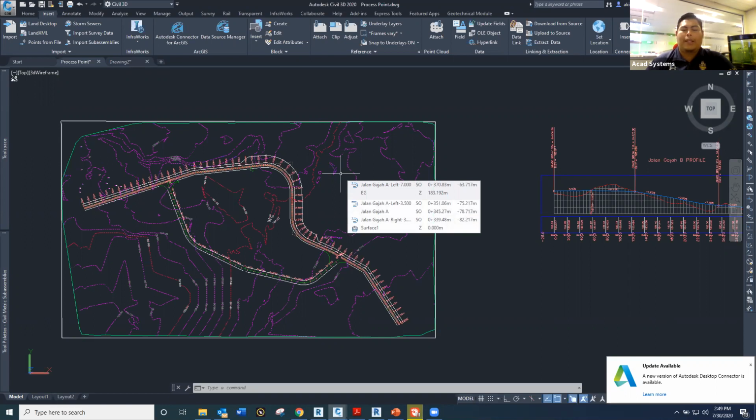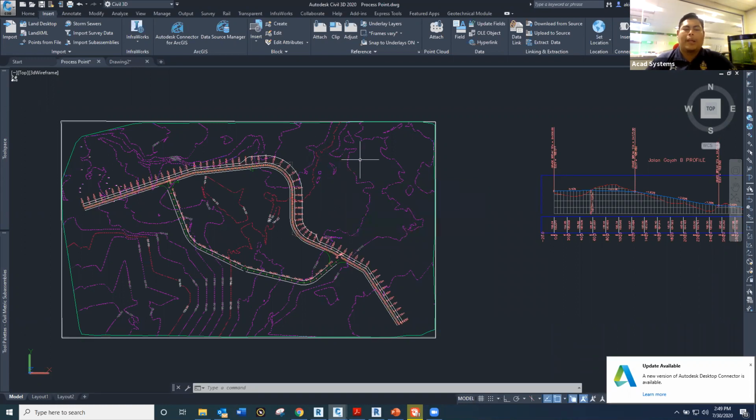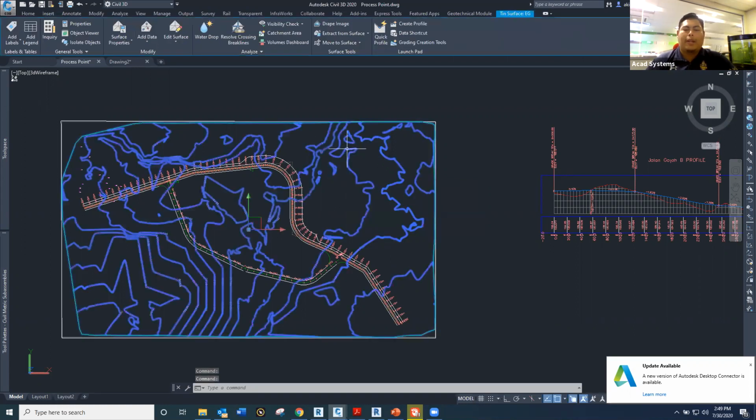For instance, in this case, Autodesk Recap reads LiDAR files very, very well. If you're going to use other formats like GeoTIFF, JPEG, or any kind of photo, it's also workable, but it may be a little bit hard to generate the surface. And the surface that is created, this is just a piece of the survey file that I took, okay?